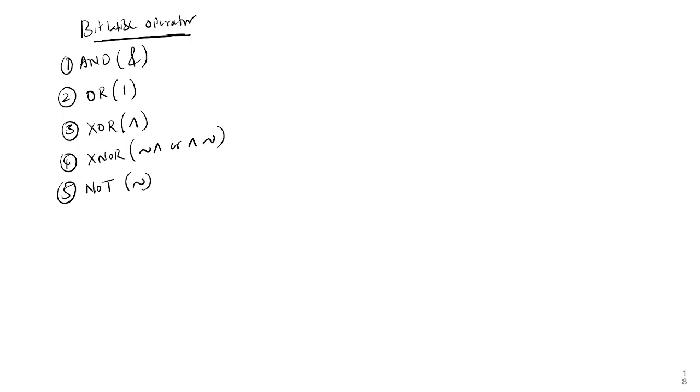So this symbol. Okay, so what are these bitwise operators? Suppose you take reg [1:0] A comma B. Okay, this is 2 bits, and reg [1:0], let us take C. Okay, so initial, okay, C equal to A and B. Okay, I am doing bitwise operator.